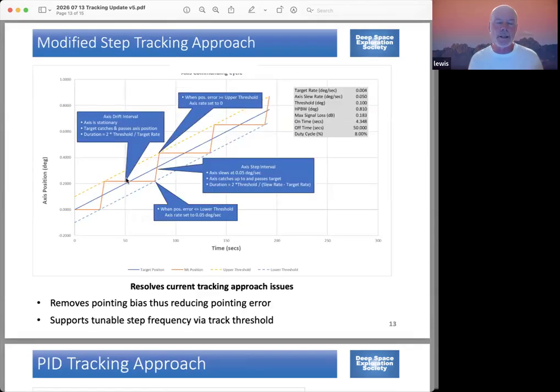And what I'm really stressing is that in the way I view tracking accuracy, there are two aspects of it. How accurately the encoders read the actual position, and that's independent of how you track. And then there's the tracking aspect of how close it keeps the mount on the object. And you have to combine those two errors, for both axes, to get an actual off-boresight tracking error.